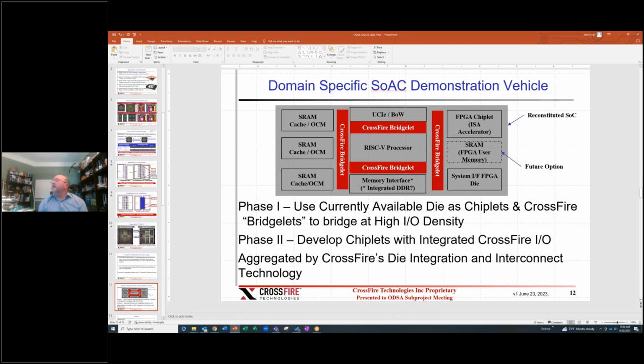And then these are just some of the things that we think would be an interesting addition. I don't think we're going to hit all of them, but right now I'm most focused on the FPGA chiplet. We're calling this the application programmable array instead of a field programmable array, because the idea is it's part of a chiplet that's application specific. Typically going to work with a processor, either as an instruction set coprocessor, or as a preprocessor to resources already on another SoC. But the possibilities are really, really endless.